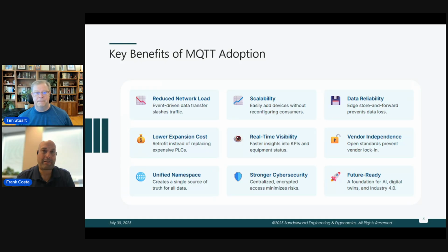Yeah, absolutely. A lot of the new IoT sensors come with the ability to publish to an MQTT broker baked in. They might come with other protocols as well. Modbus is nice and open, but it doesn't have all the features that a newer protocol has. But I have not seen, if you see IoT attached to a sensor, you're going to see MQTT attached to it, or the ability to publish JSON. It's all the same thing.